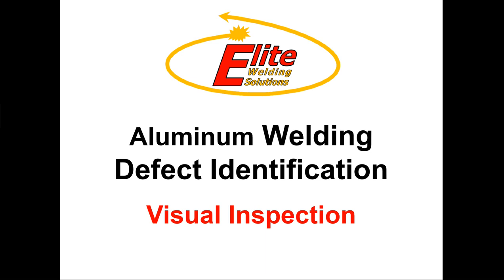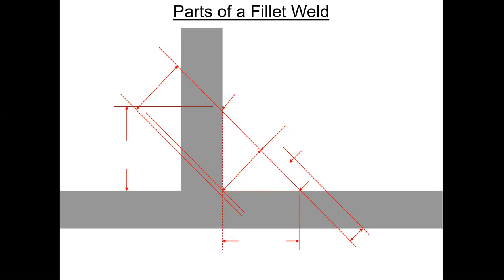Okay, the actual visual inspection side of it. Let's talk about, and again, I'm going to stick with terms here, terms that I'm going to use over the next half hour or so to make sure we're all on the same page. So the toes of the weld, the toes represent that area between the base metal and the weld metal, that one spot right there.